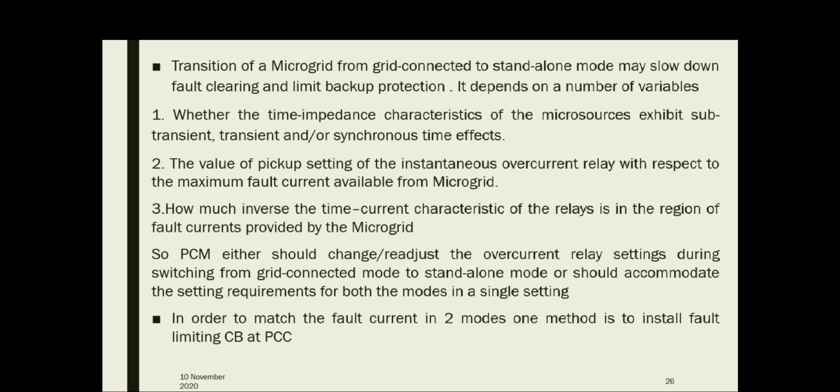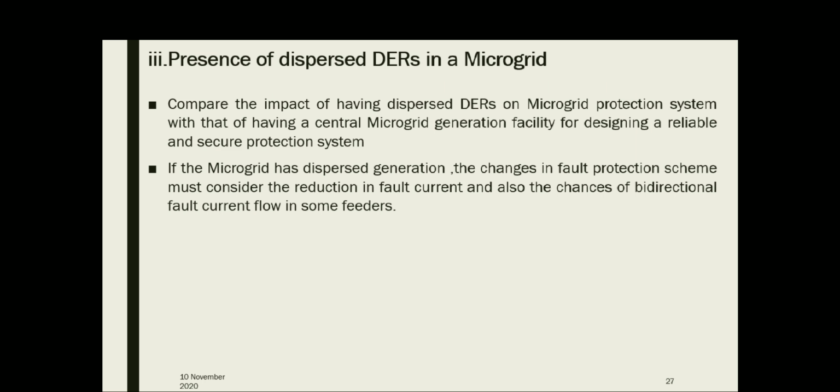And third point is how inverse the time current characteristics of the relays are in the region of fault current provided by the microgrid. That is, how much the operating time changes for a change in the fault current.